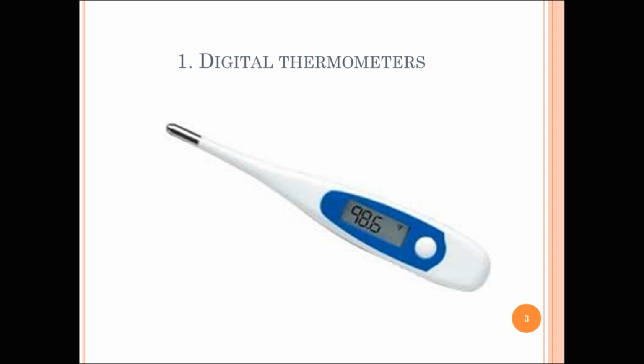The accuracy of the actual temperature measurement will be considerably less because of the deviation of the individual thermocouple or resistance temperature detector from published tables, and the usual problems of sensing any physical variable precisely. Sharing of a single digital thermometer among many thermocouples or resistance temperature detectors is possible by using scanner accessories. Moreover, interfacing to printers, computers, etc. is also possible as digital information is already available.